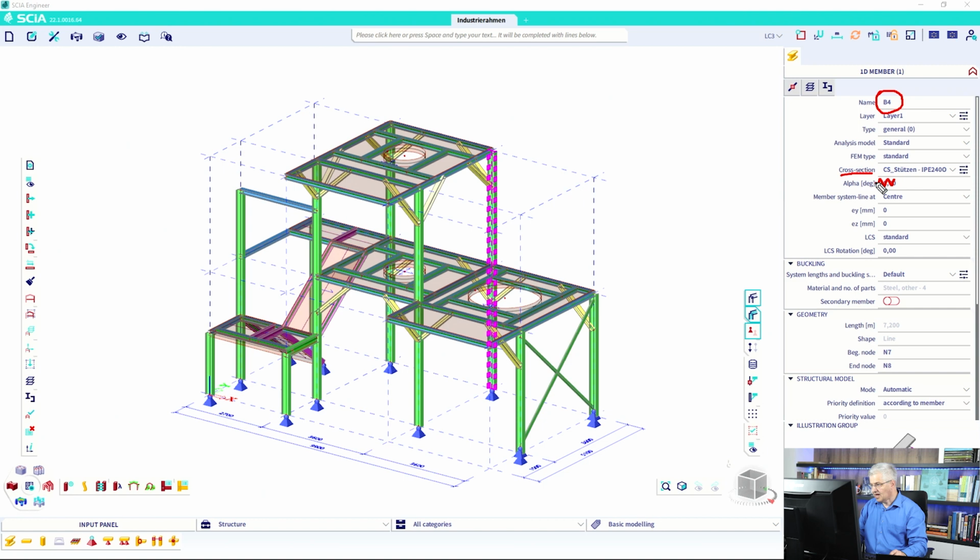The rotation with alpha is not imported, because then you disconnect the local coordinate system and the cross section. So I don't think it's a good idea to use it. I use it only if I must, because then the evaluation of the internal forces and the buckling lengths is more difficult, as you have the y and z axes rotated, so it's not good.